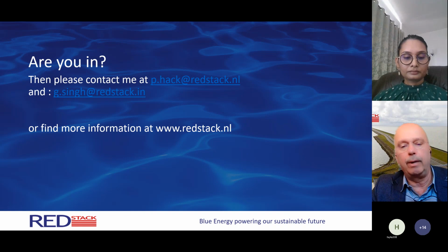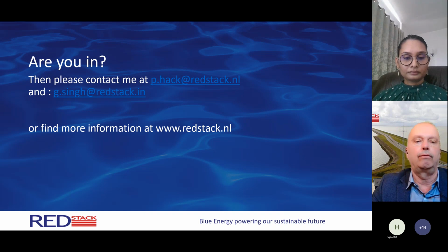Let's call it anything bigger than a millimeter or so to filter out. And the second step, then we do fine filtration to remove the algae and so on to protect the stacks. But this pre-treatment of both the river and the seawater, of course, removes a lot of plastic and other garbage that otherwise would be floating into the sea. So you could say we help cleaning up the rivers.